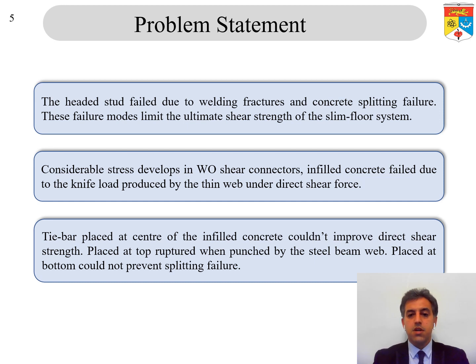But the problem of those shear connectors is that the headed stud fails due to welding fracture and concrete splitting failure. Those failure modes limit the ultimate shear strength of the slim floor system.